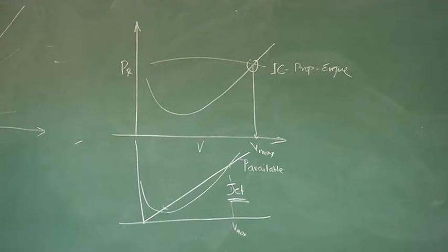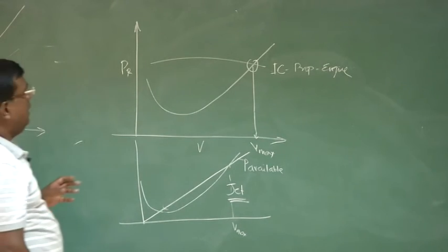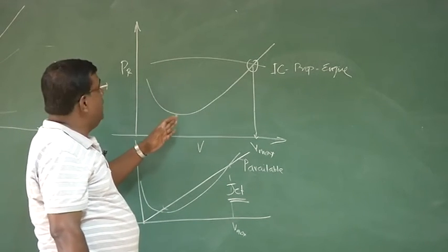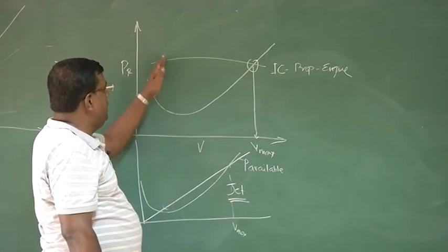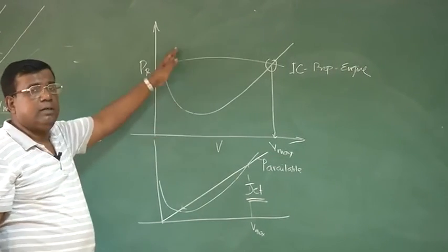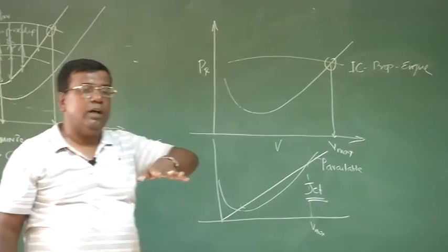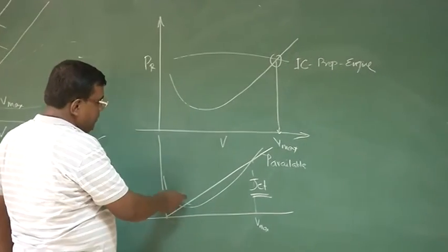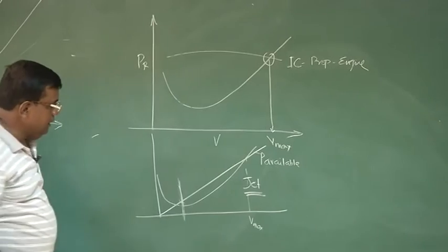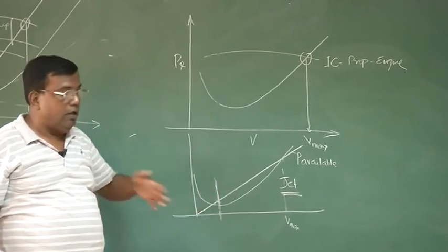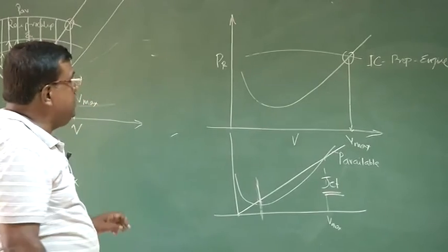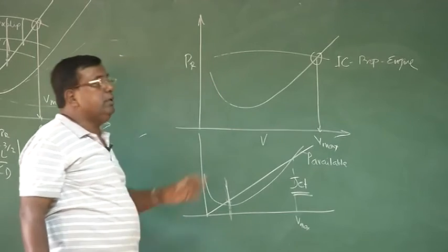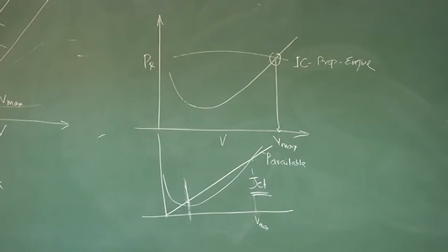Okay. But as a designer, we need to understand also that if I am coming for a landing, right, I'll be operating somewhere here, right? So I have got enough excess power. So in case of any eventuality, I can use that excess power to come out of it. However, when I am using a jet engine, you could see that this excess power near the stall or near where you're landing, that time the excess power relatively is less compared to for such engine. So this is one distinction a designer needs to keep in mind.